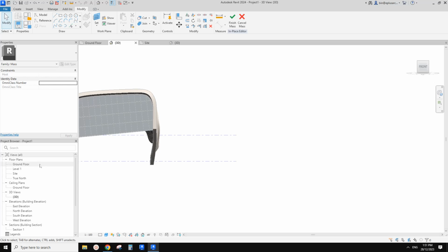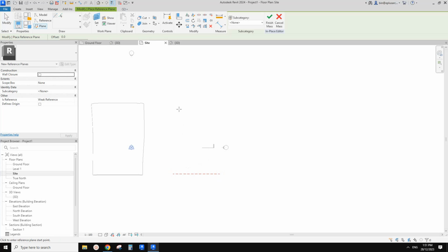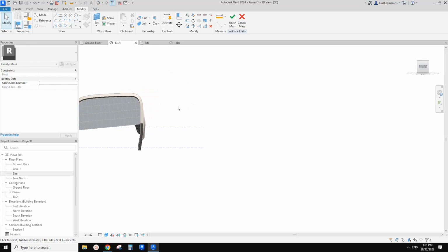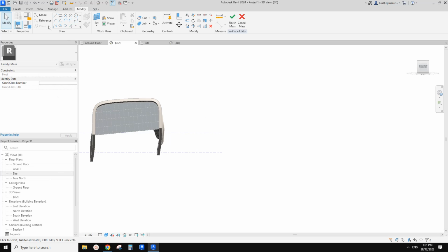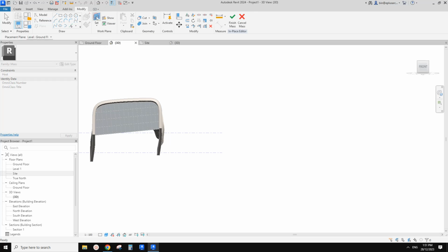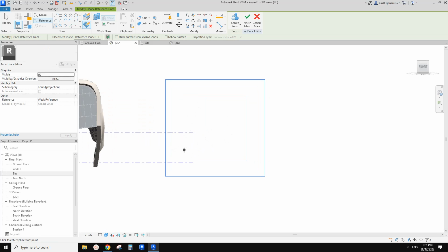Okay, so let's just do this. I'll go to side plan. In this side plan, I'll just create some reference plane. So 1, okay, so I only need 1. I'll probably name it 1. Now go to 3D view. Okay, and we can create reference line, spline through points. I'm going to use draw on work plane and set work plane, and go here and pick this reference plane 1. So now I know that all these points will be placed on that reference plane we just did.